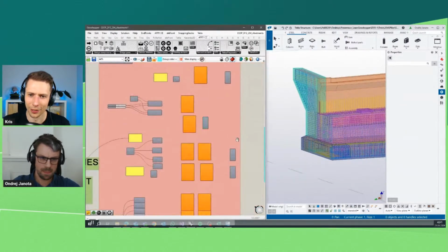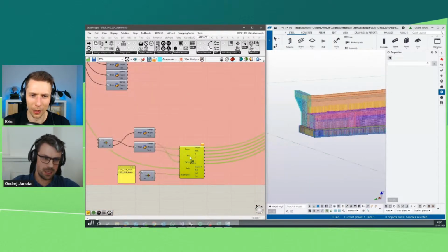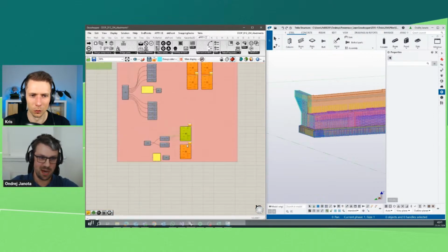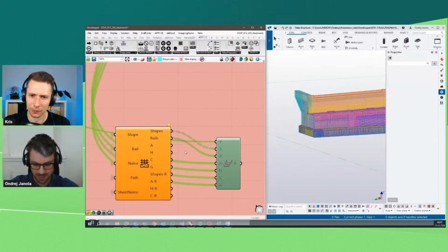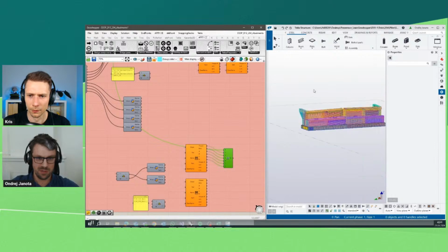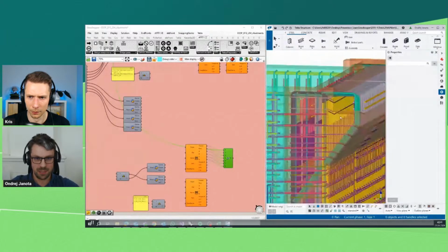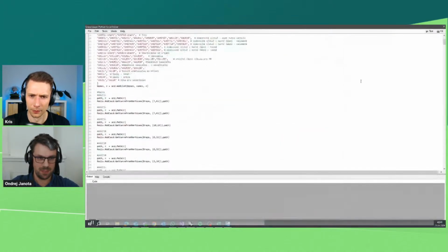This is the common error with the cover, that we have to have minus or plus. It depends. But we know it, and you have to live with it, and it's not so hard to fix it. You will see it a little bit later. Always, you need to do the check. If you just copy the reinforcement from the one part to another, always do the check and see if everything is okay. But right now you see that we reinforced the second abutment in a matter of minutes.